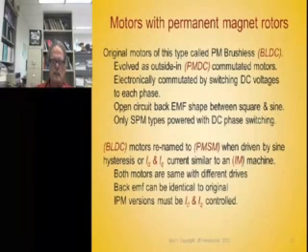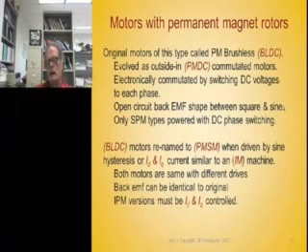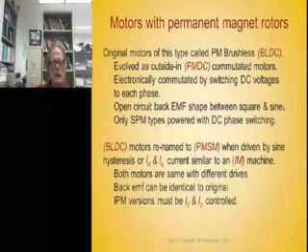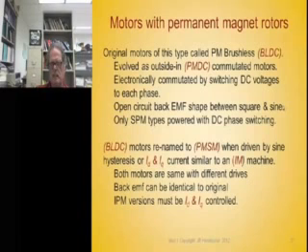If you take these motors and you spin them like a generator, you drive them. Take a motor and stick a shaft in a drill press and spin it with a drill press, and look at the voltage across the lead wires, and put that output on a scope and see what its shape is. You can see its amplitude, frequency, and its shape on an oscilloscope. So if it's square, it's thought that a brushless DC motor needs to have a square wave back EMF, and a sinusoidal driven motor is thought to need a sinusoidal back EMF. Now that's not necessarily true.